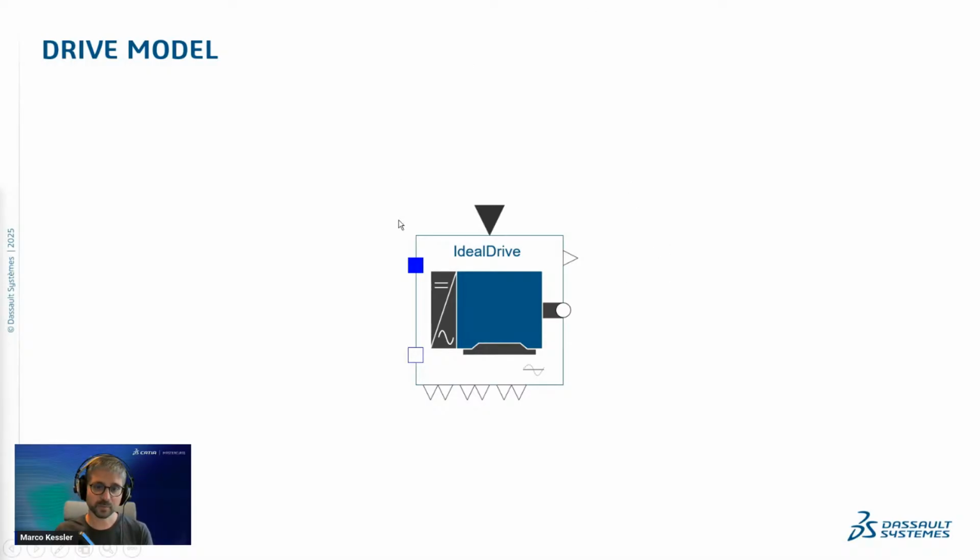So this drive model is not modeled in a very deep physical detail. So if you look inside, you don't have electric components. It's just modeled to act like a drive from outside. So you have this connector here where you request a torque, and this torque could be limited. And then you will get a torque at the flange, and the required power which is needed to drive the flange is drawn from the electric side. That's what this model does.